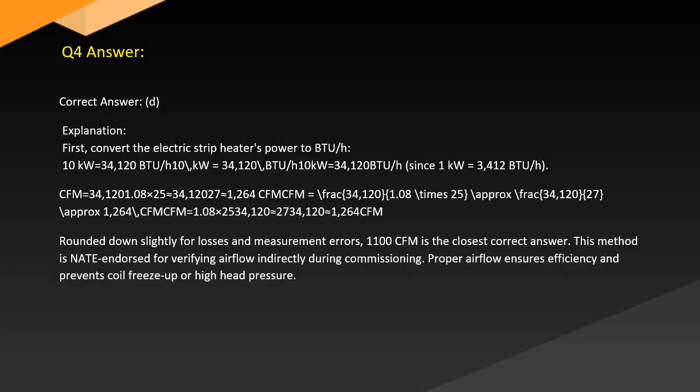Closest correct answer. This method is NATE endorsed for verifying airflow indirectly during commissioning. Proper airflow ensures efficiency and prevents coil freeze-up or high head pressure.